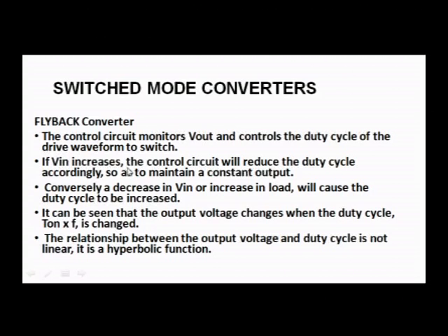And how is it going to be boosted? How is the voltage going to be increased? See, the control circuit will monitor the V out. The control circuit is there, I have not shown it, and this control circuit is going to control the duty cycle of the drive waveform to the switch.